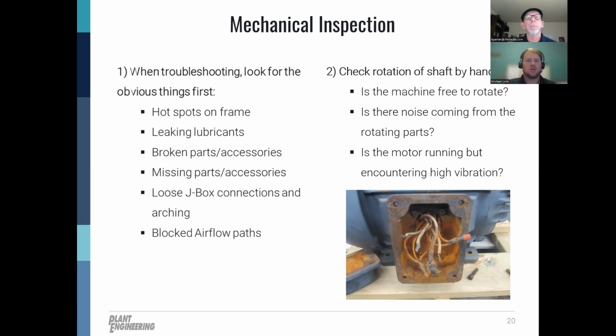If you've got a sawmill, sawdust particles, rock dust at a crusher or a quarry, concrete, metal slag, all of these things, you've got your motor running there. It's serving some type of pump or rotational process, and then you've got all of this stuff going around in the environment around it. Make sure that your process isn't leading to a blocked fan or blocking air movement coming